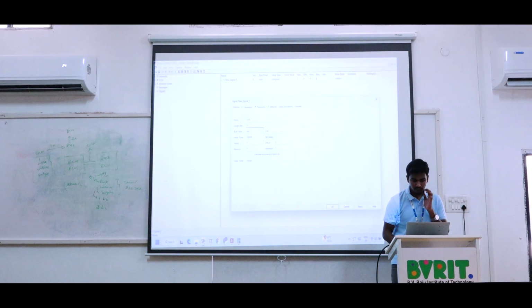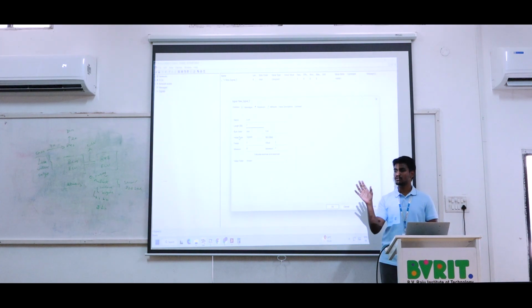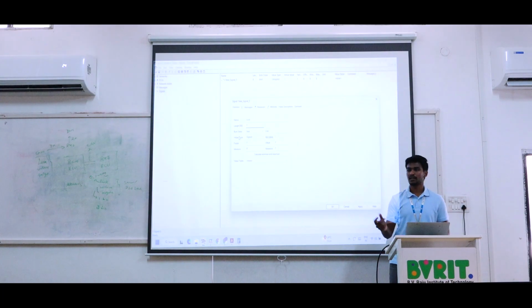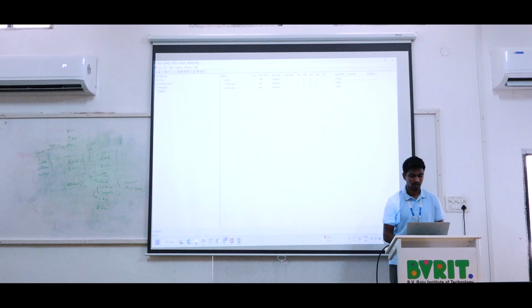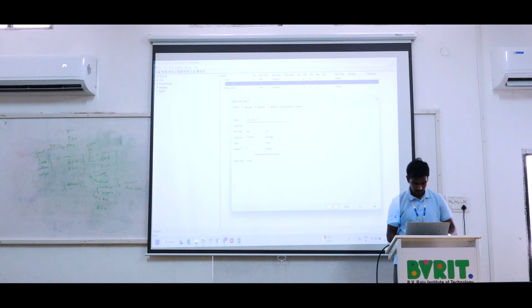I will give the length as 1 bit. If the value range is 0 to 255, you can use a factor of 1 and a length of 8 bits. If the value is more than 255, you can take the correct factors with multiplication factors. Okay. I am using unsigned. Minimum, maximum. Then just press Control C and Control V to copy the signal. You don't need to create it again, because if the minimum and maximum values are the same, you just rename the definition only, because the length in bits and value type will be saved the same.